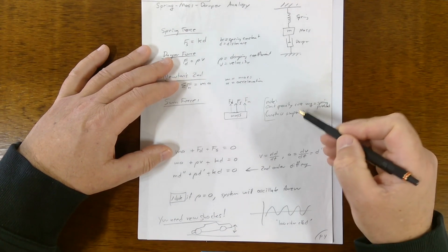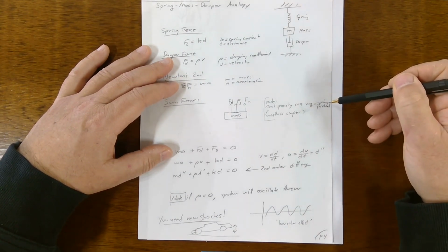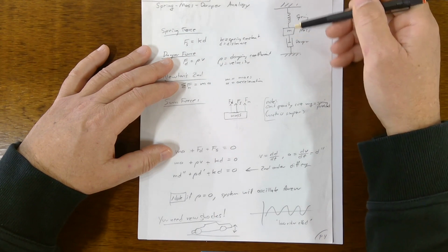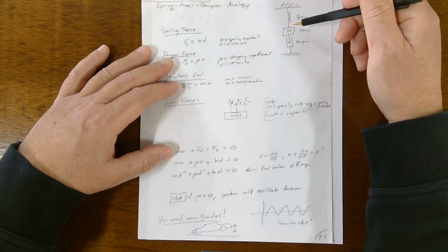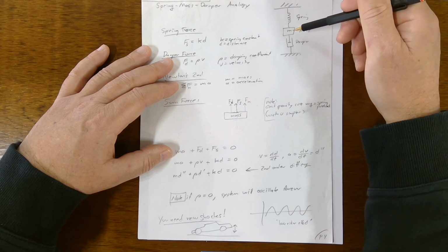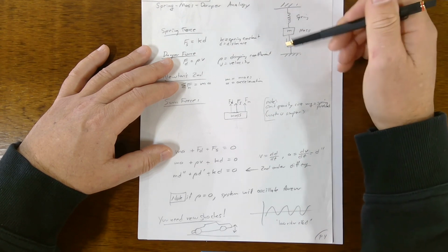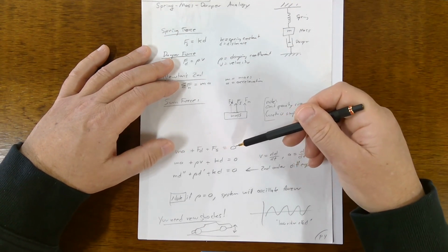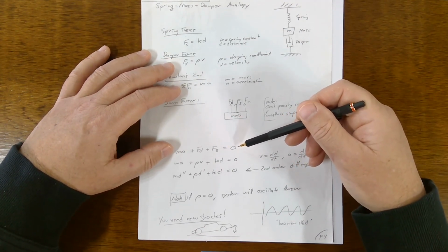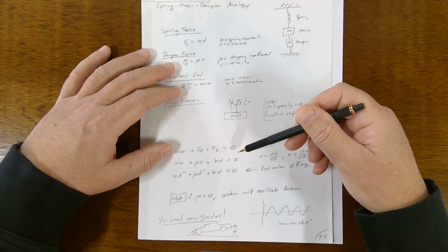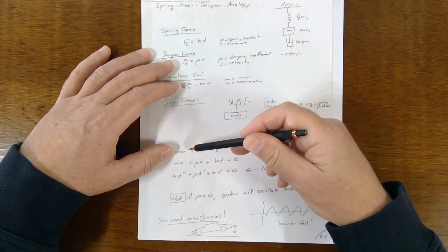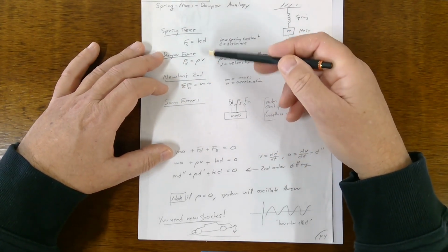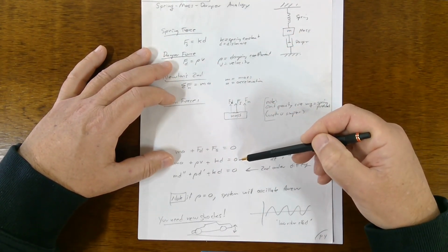And I'm omitting gravity because that's counteracted by the spring preload, right? When you first hang this guy, gravity's going to be pulling it down, and the spring will deflect a certain amount, and it'll be at an equilibrium there. So we can just ignore that part of it just to make the math simpler. And we're only concerned with the forces that are acting when this thing is moving. Okay. So anyway, these are summing up the three forces on the free body diagram, and then substituting these equations in there, we get this thing.